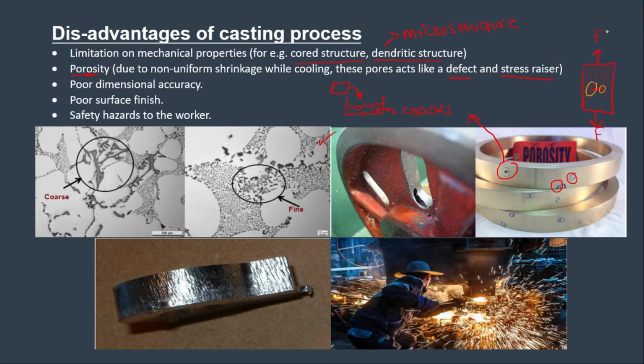Maybe you are applying 10 Newton force here, but because of this concentration of force at the extreme edges of this pore, this edge might experience a force of 15 Newton. This is how it acts like a stress raiser.